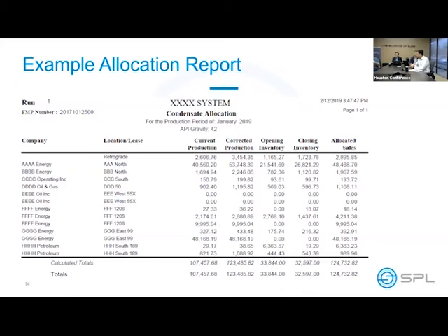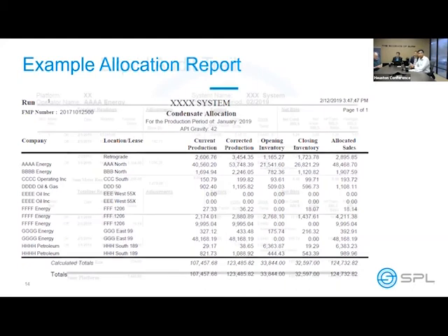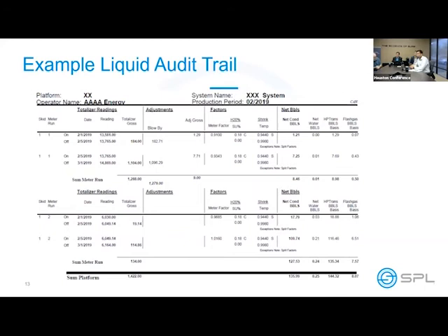On the previous slide, we had an example of the audit trail where we were doing that actual calculation. It did not calculate flash gas. Normally, we will meter flash gas and then use our oil allocation, or our oil net volume, and those factors calculated here on the right-hand side in order to allocate the flash gas itself. So this is a direct example of how we would do that.